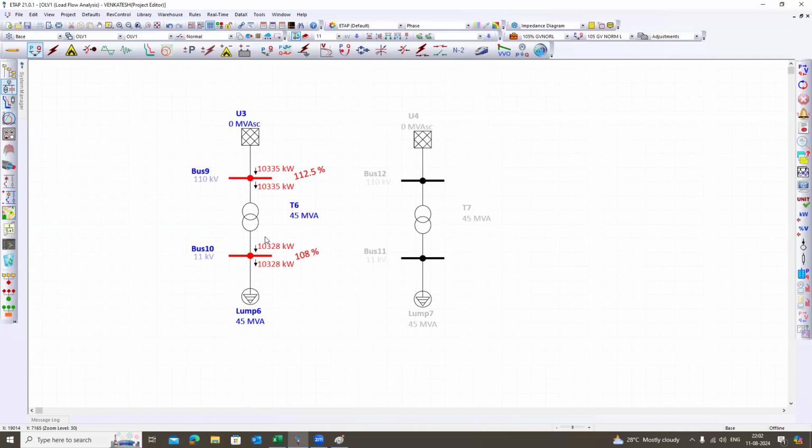Okay, sir, thank you. Sir, I have one doubt. Here we are fixing our upper limit and lower limit, right? But how will we decide the step size? In a station transformer or grid substation, we normally see 17 steps, each of 1.25% or so, but in distribution substations we normally use steps of 2.5%. How will we decide the step percentage?